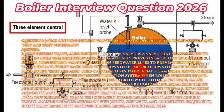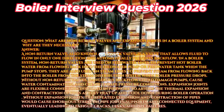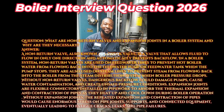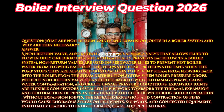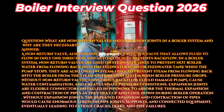Question: What are non-return valves and expansion joints in a boiler system and why are they necessary? Answer. A non-return valve, also known as a check valve, is a valve that allows fluid to flow in only one direction and automatically prevents backflow. In a boiler system, non-return valves are used on feed water lines to prevent hot boiler water from flowing back into the feed water pump or feed water tank when the pump stops.